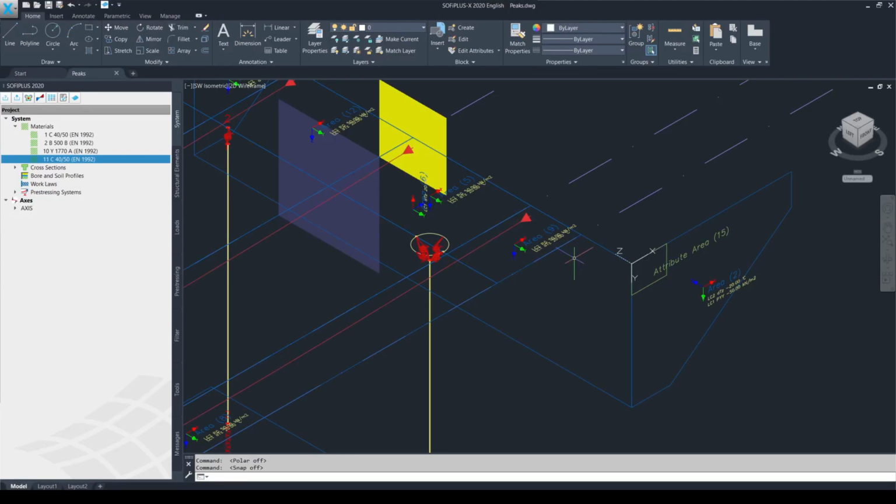The remaining problematic part that I haven't mentioned yet how to solve is again the intersection of the vertical wall and the bridge deck. Usually on the vertical wall along the edge, the quad elements are undesignable.